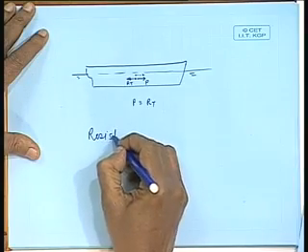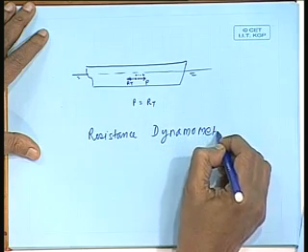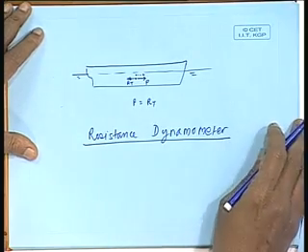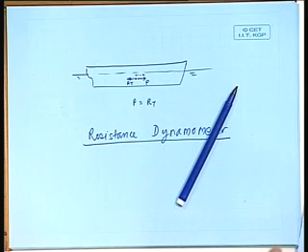Now, one thing we have to know: whatever arrangement you make with this toe hook, how do I apply the pull? It must be applied from the top somewhere, isn't it? So, what we have is what is called a resistance dynamometer. This resistance dynamometer is a device which is held by a carriage on top of the model, the carriage being held separately on rails mounted on the towing tank. So, the carriage and model have no connection except through the dynamometer.